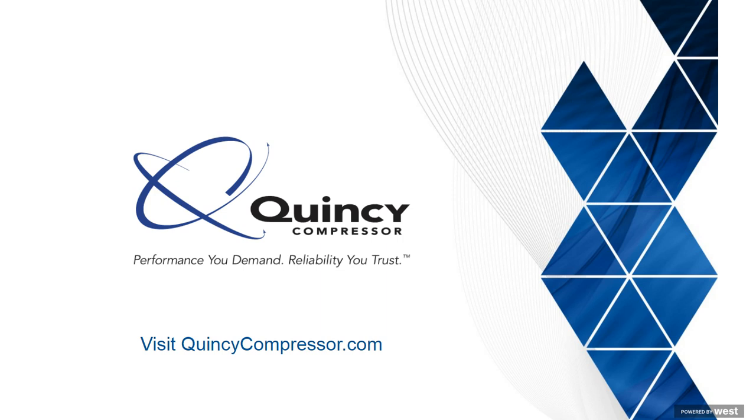Okay. It's another question from this questioner. What are some of the core components that are being targeted for efficiency? All the obvious ones: controls, motors, the full drivetrain, air ends, almost everything on the air compressor: motor, gearbox, air end, unloader, controller, piping, coolers, discharge, various types of regulation within the compressor. Everything on the air compressor is up for being targeted as an opportunity for improvement.